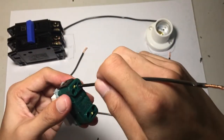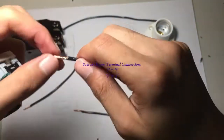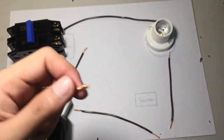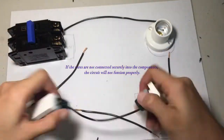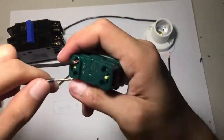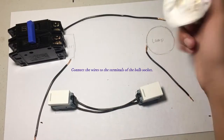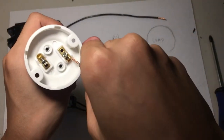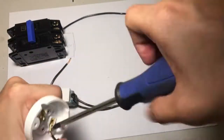As mentioned earlier, in connecting the output terminals of the switch, it should be terminals 1 to 1 and 3 to 3. Be sure that the wire is connected securely into the switch, so that when you pull the wire, it won't come off. If the wires are not connected securely into the components, the circuit may not function properly. Next, prepare the screwdriver to connect the wires to the terminals of the light bulb socket. Insert the wires into the holes and secure the screws in order for the wire to stay in place and not get detached.